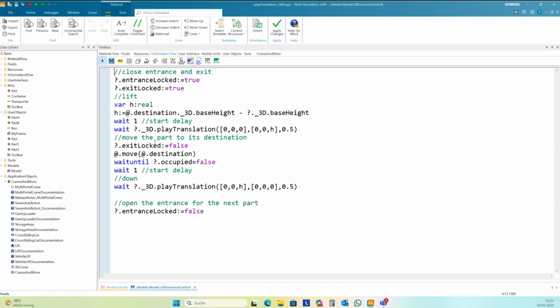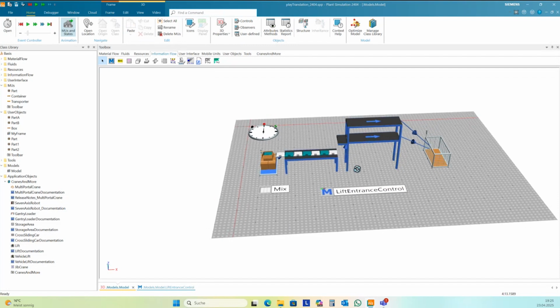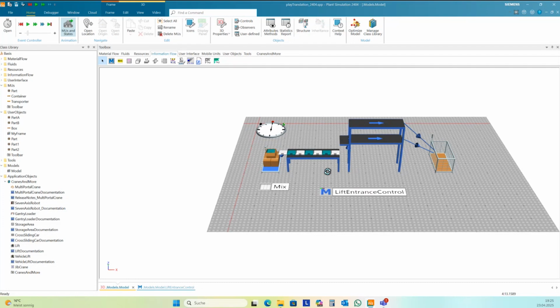There's another one here. It's plate rotation, and plate rotation you can use to let elements rotate directly. And if you need some very special turning plate, for instance, or turning device, then you can use this plate rotation to animate this, for instance, a conveyor to create rotations.